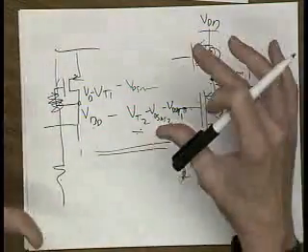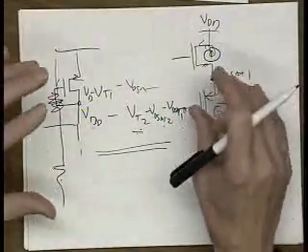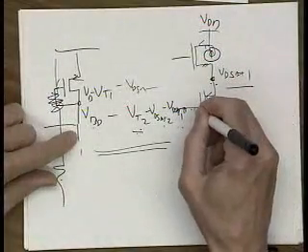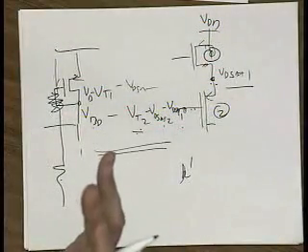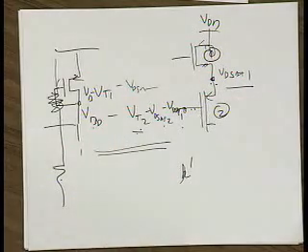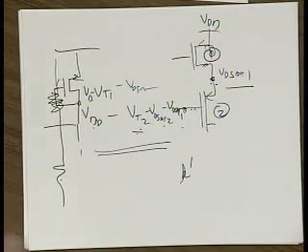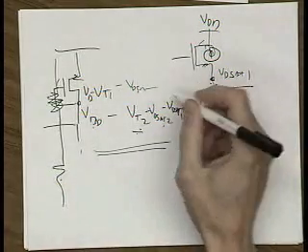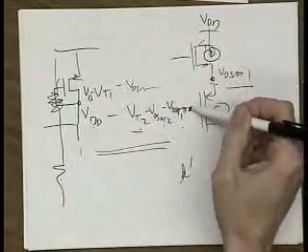In fact, you can go to an extreme in this. It's quite often done because of the problem of trying to set these bias voltages. It's called replica biasing. You can almost make a duplicate amplifier. Imagine this: a duplicate amplifier, set the inputs to 0, and pull voltages off that amplifier to bias up your amplifier. You say, wow, that sounds pretty extreme. But it's difficult to get these voltages right. The case I showed here was fairly trivial, but sometimes when you have more complicated circuits, you might go to that extreme.